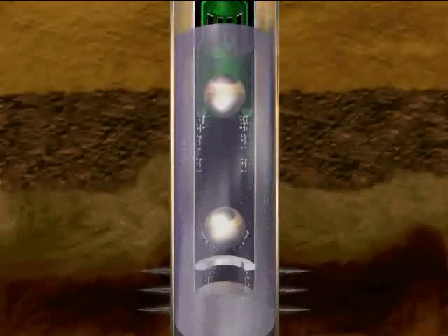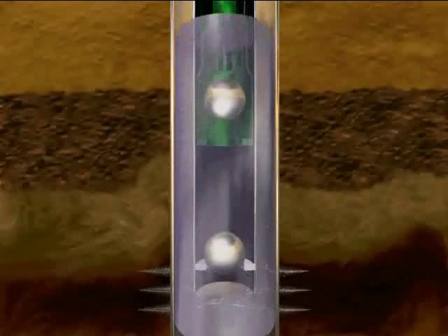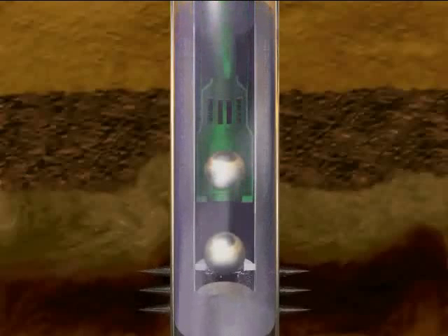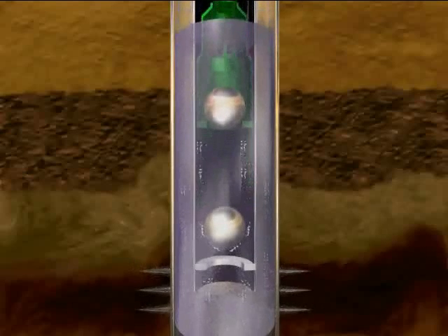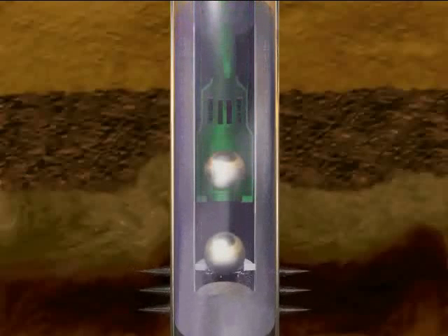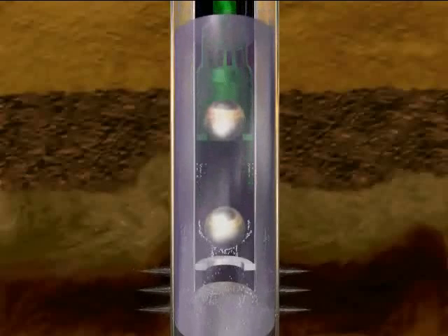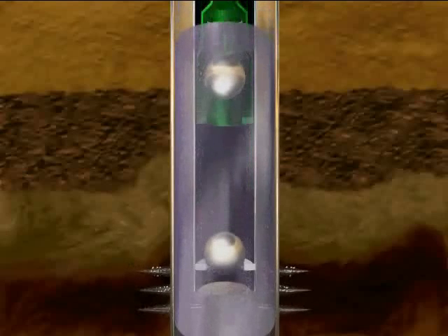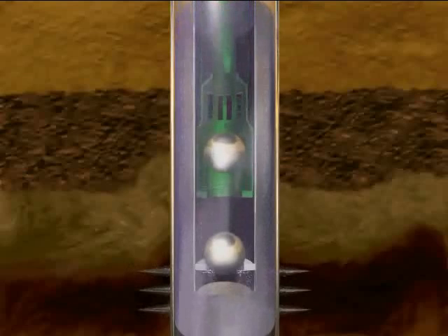Here are the perforations. Gas coming out of solution in the upstroke. The fluid level here moves down on the upstroke as fluid is entering the pump, and then it goes back to normal on the downstroke as the fluid continues to come out of the perforations.